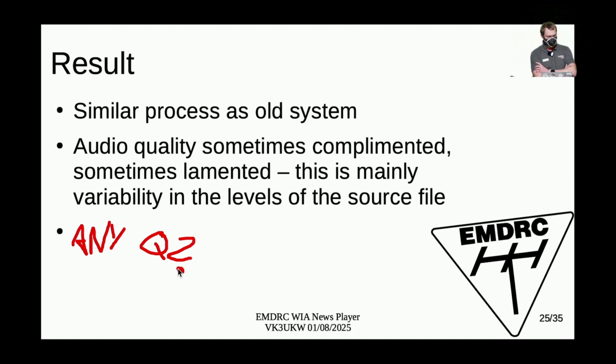Essentially you just type into the control channel, turn the radio on now, and the radio starts transmitting. Whatever you send in via the audio channel is what gets transmitted. Then you type in, turn the radio off, and the radio turns off. Of course, with a computer you can automate that, so instead of you clicking a button that says transmit now, a program in the computer does it.